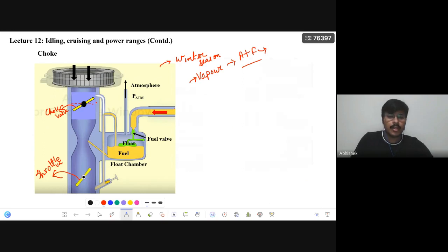And how can this be done? This is done when you press that choke switch. The valve is closed here. Once the valve is closed, in a closed chamber the air is not flowing through it. Then what is there? Vacuum. As it is closed, some vacuum will be created here, or there will be a very low flow of air, but still there will be some vacuum, and the pressure here will be lesser than atmospheric pressure.